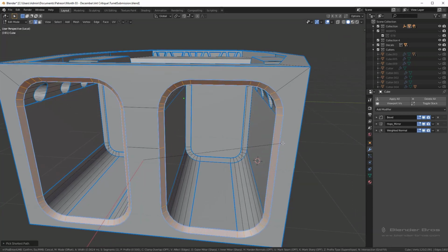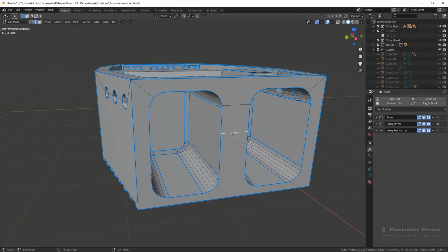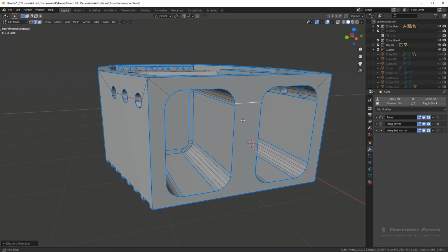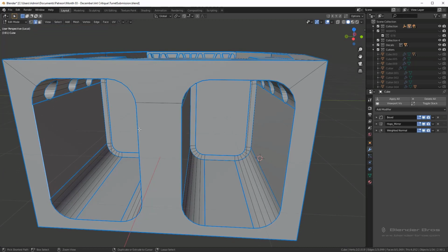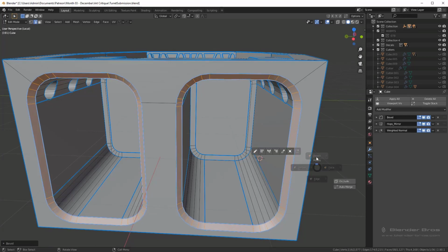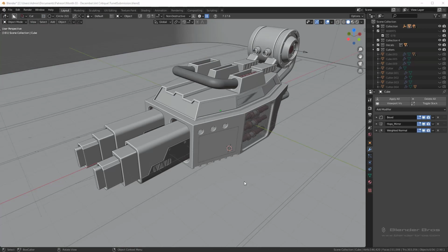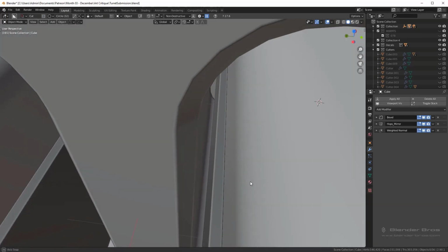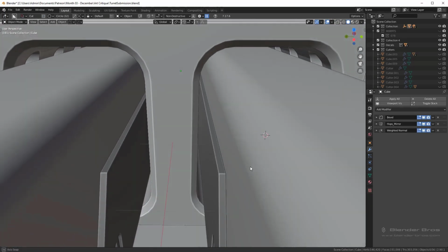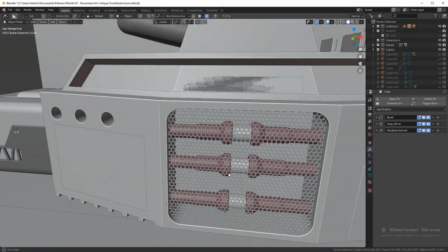you're going to see it does a nice chamfer with no issues. We're going to do a really small one though. And we don't need these edges either. Not sure what these are doing. We'll dissolve out what we can, I guess. Try this one more time. Control B. And now check this out. This looks a lot more profound now. So definitely try running chamfers wherever you can. They tend to make the model a bit more robust and just look nicer. So let's go ahead and move on.